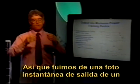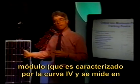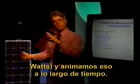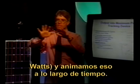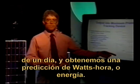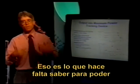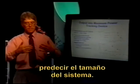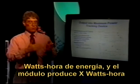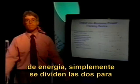So we've gone from an instantaneous snapshot of output from a module, which is characterized by the IV curve and measured in watts, and we've animated that over time. We've looked at that power output distributed over a day, and we end up with a prediction of watt hours, or energy. That's what we need to know to do our system sizing predictions. Because if your load in a particular day needs so many watt hours of energy, and your module produces so many watt hours of energy, you simply divide the two, and it tells you how many modules you need.